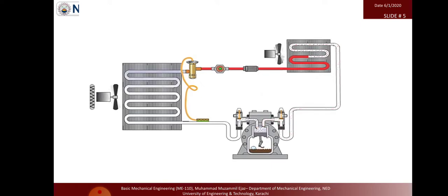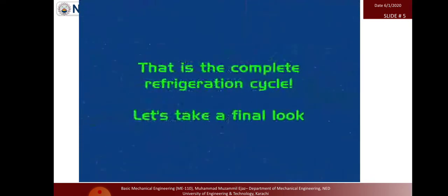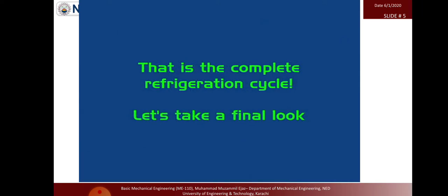Like I give an example of a perfume, the body spray or body deodorant: you have a high pressure liquid inside the vessel. When we press the button, the high pressurized fluid goes outside into the atmosphere, which has a very low pressure compared to the inside of the vessel, and due to that we have a cooling effect.